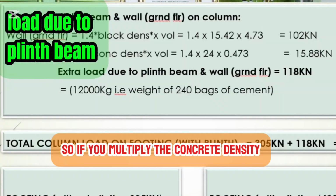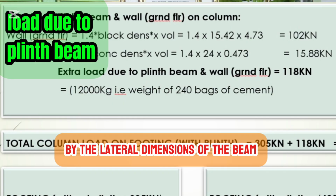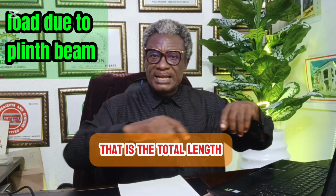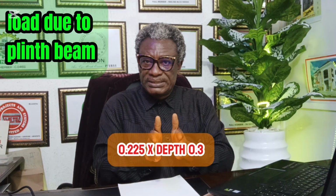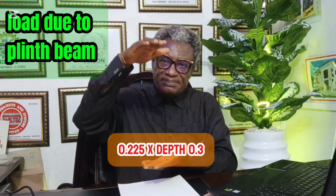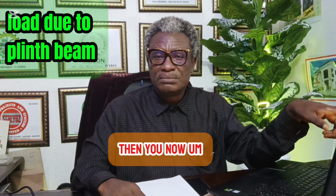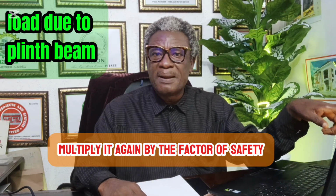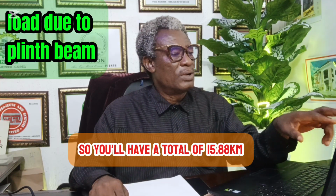So you multiply the concrete density, which is 24 kilonewton per meter cube, by the dimensions of the beam, that is the total length, which is 7, multiplied by the thickness 0.225 by depth 0.3. Then you multiply it again by the factor of safety, which is 1.4. So you will have a total of